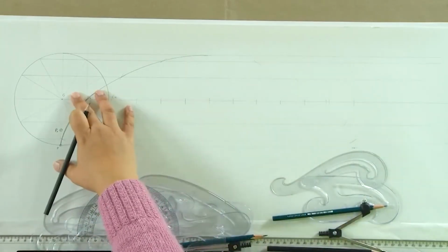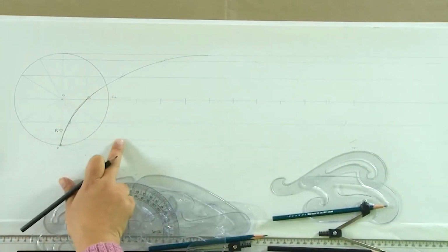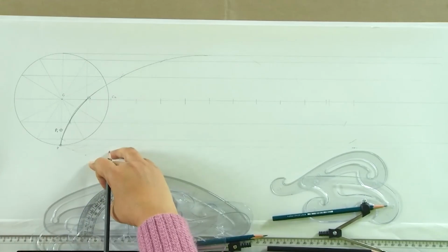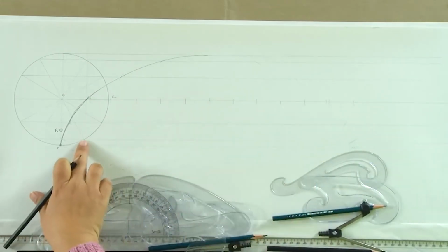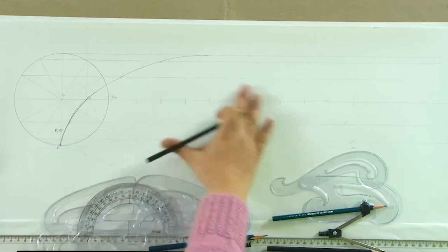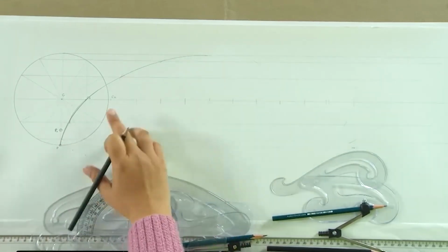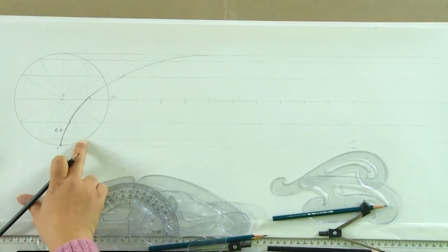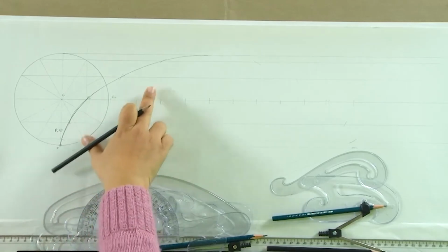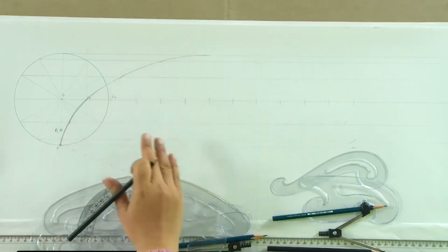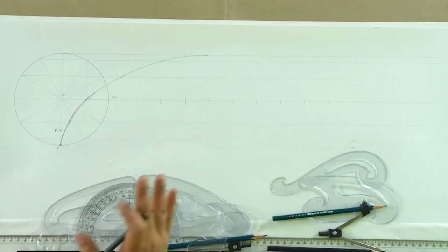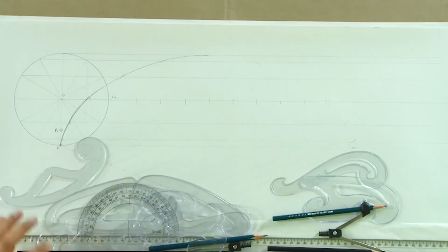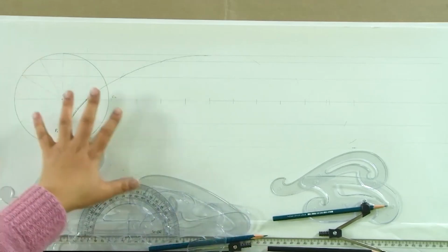And exactly in the same manner, instead of these parallel straight lines, we would be drawing concentric arcs at the same distance from the center. So, this is exactly the same process. The only thing is, instead of tracing the points on these horizontal lines, we would then be tracing the points onto those parallel curves. That is how we would draw the epicycloids and hypocycloids. So, this is the process to draw cycloids.